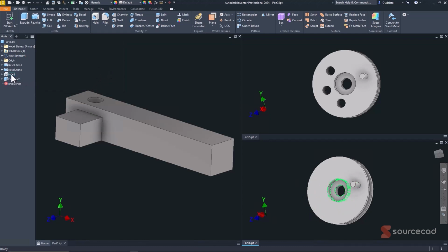So with that, you can create your own. Again, you start with the part, you make the part, and then you'll have something very similar. Copy it. And this is again where the naming comes in. Name your extrusions, name your sketches. It just makes it easier to work with once you're done. And so that takes us through the revolve command and the hole command.